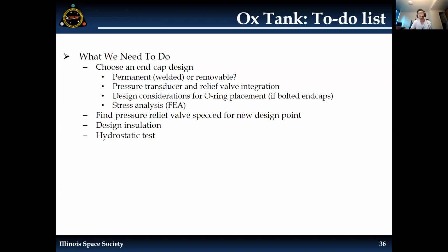Question from Nahar. Okay. For insulation, we are choosing between fiberglass and rubber, right? Yes. And the thickness is variable depending on our tests. We want it thick enough such that the loss of heat is reasonable, but we don't want it too thick such that it again eats into our mass cost. Good questions.